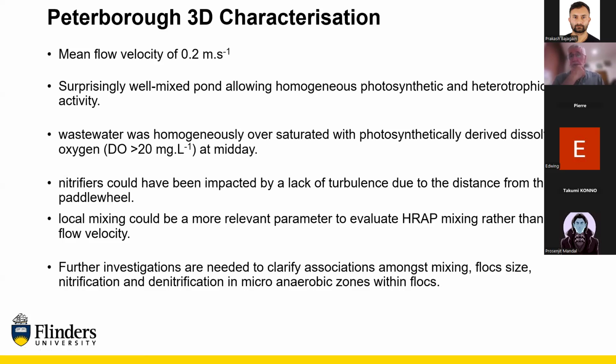Photosynthetically, dissolved oxygen was really high. It was oversaturated. It was over 20 milligrams a litre at midday. The rates I've shown you in the pond were corrected so we could compare the 26 points. But during the day, it was up at 200% saturated in the diurnal cycle, without us correcting for that cycle at each time of measurement.